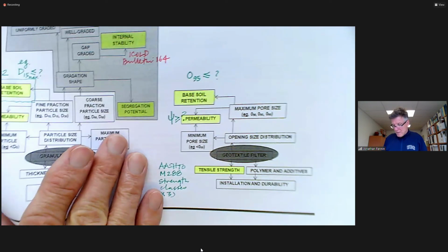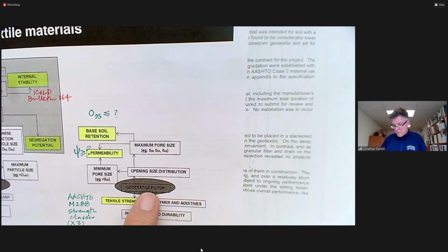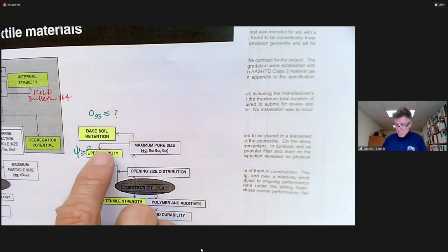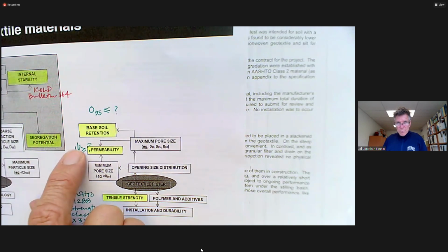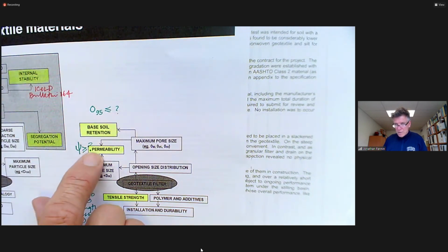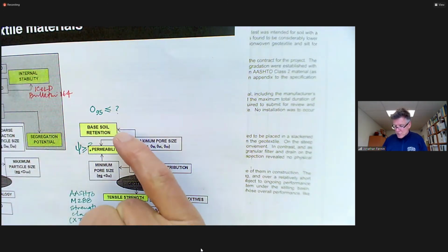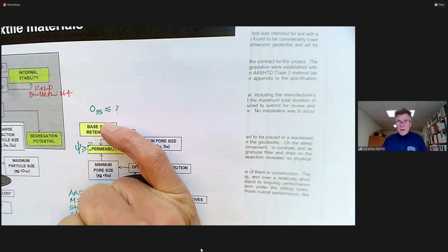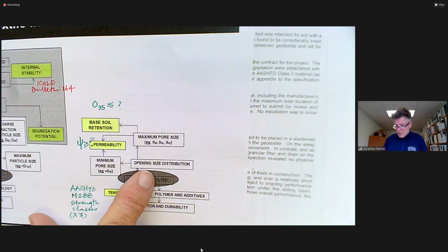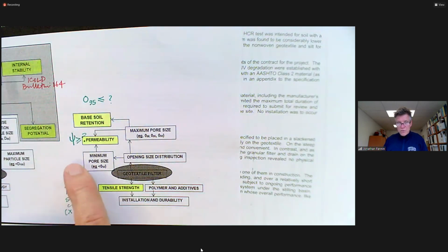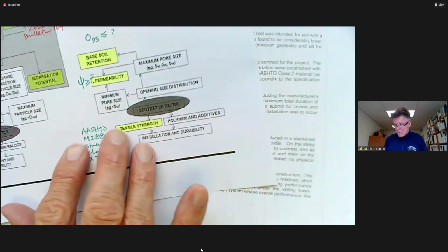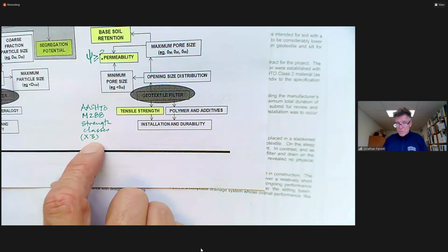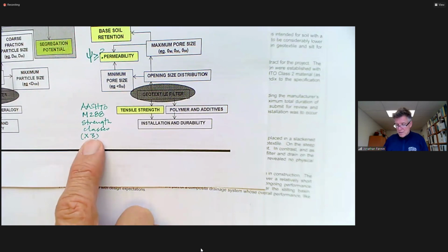In specifying the geotextile filter, we looked at empirical rules. I looked at a number for base soil retention. Other than wanting a reasonably permeable material, I didn't place too much emphasis on an index value here. Rather, we defaulted to gradient ratio and hydraulic conductivity ratio testing to look at the soil geotextile compatibility in combination. And I spec'd a strength class that was a medium strength material.